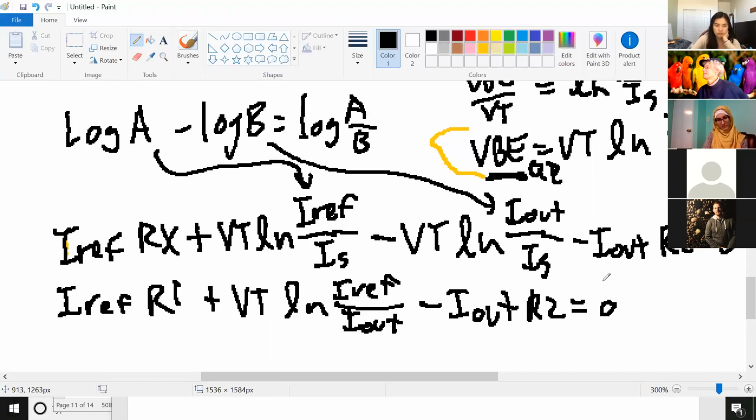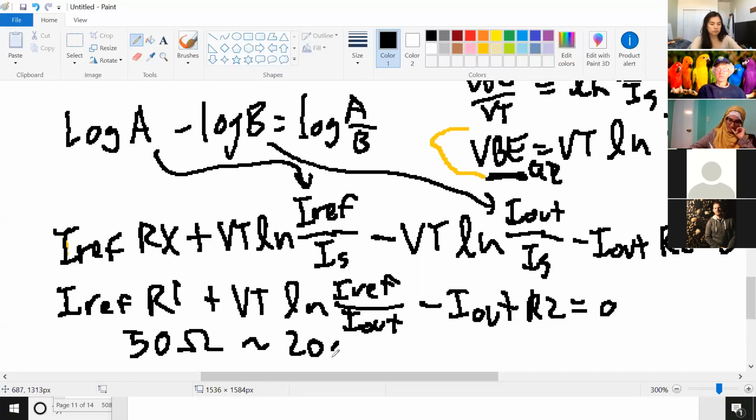Determine the resistance. Yeah, but you've got two unknowns, and now you're a designer. I just gave you a promotion. To pick one. Pick one. Exactly. So it turns out that for degeneration resistors, somewhere between 50 ohms and like 200 or 250 ohms is a good size. So I would just pick one.